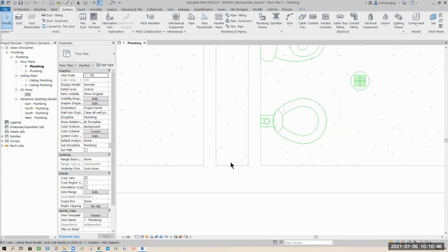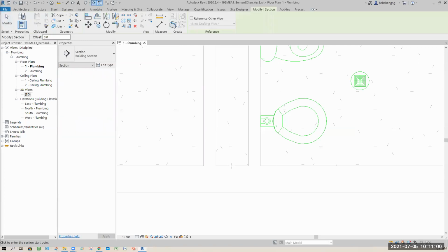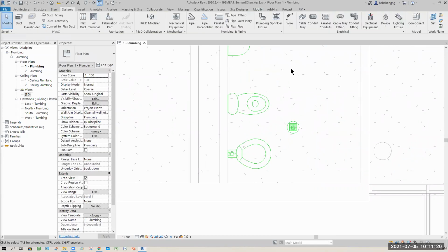So you place it in the center, but how do you justify it in the center? You need something called a reference plane. Because when you do sectioning, you can't snap or determine exactly the midpoint of the opening of this wall. You can see you don't get any O snap. It doesn't come with it. See that? Don't have, right? So if that's the case, then you need to get your reference plane. This is the viewer, it should be this one.